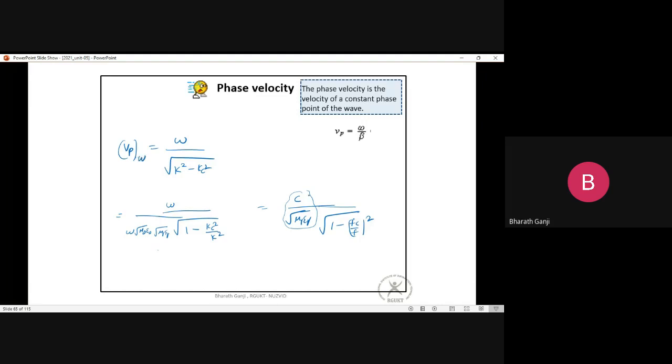Okay, so let us call this the phase velocity of the wave. Let me call v naught the phase velocity of a wave in an unbounded medium, free space or unbounded medium, where v naught is c divided by square root of mu r epsilon r. In an unbounded medium the wave would travel with this phase velocity, but because you are operating above the cutoff frequency, I can see that the phase velocity is greater than v naught.